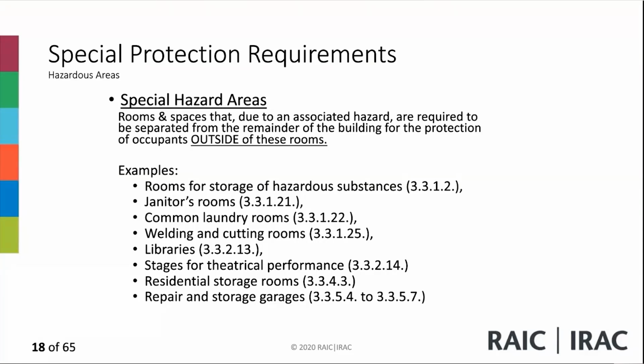Maybe if you don't store any chemicals. Take a look at 3.3.1.21. Keep reading, because I started with except as permitted, right? So when I said the 1 hour rating, I didn't look at except as permitted in 2 and 3. So what do sentences 2 and 3 allow me to do? It's not less than 45 minutes. If the building is sprinklered, you don't need to rate it.